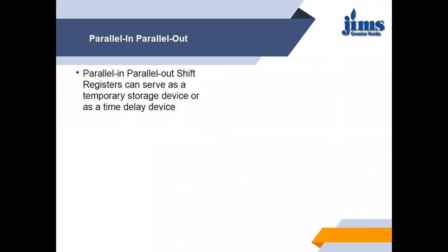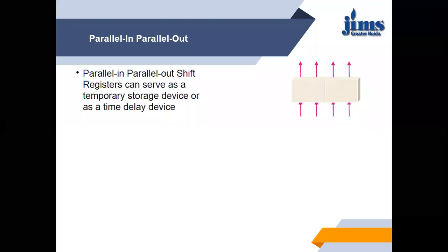Further, the last one, as we have discussed SISO, SIPO, PISO, and PIPO, that is the parallel in parallel out shift register. It can serve as a temporary storage device or as a time delay. Data is entered parallelly. We have used 4 blocks, that is 4 flip-flops. Each block represents a flip-flop.